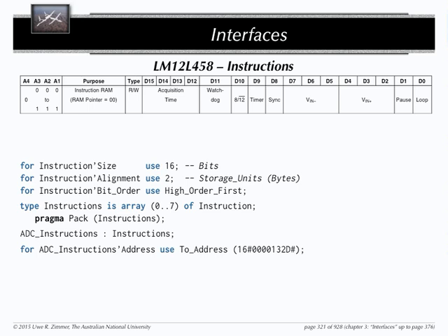So if you have an awareness that all the registers which you are now setting by using your variables will be directly accessed on hardware, each individual writing of a few bits, writing a word out on hardware, will have direct effects. Some of these effects will, for example, require that you wait for a few microseconds. Because if you power something up, an actual hardware device, it may not be ready after one CPU cycle.